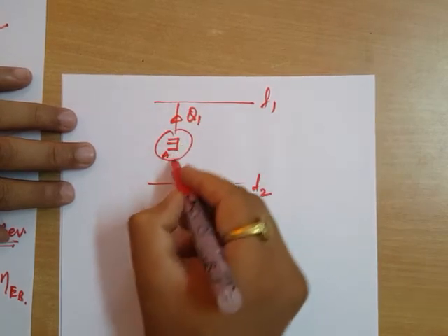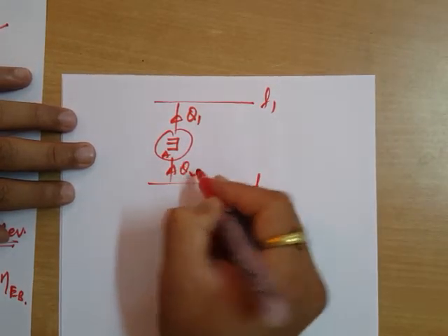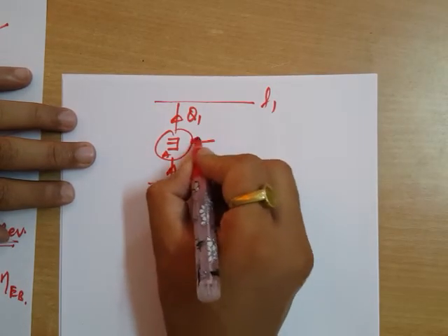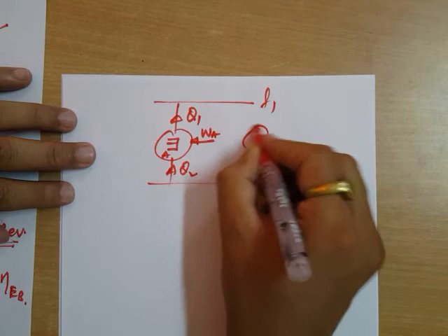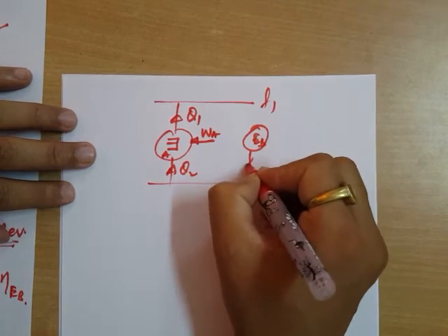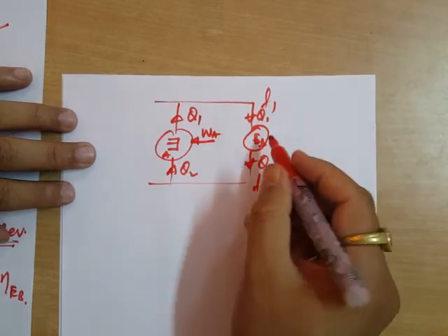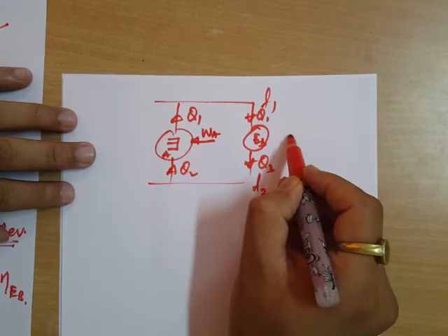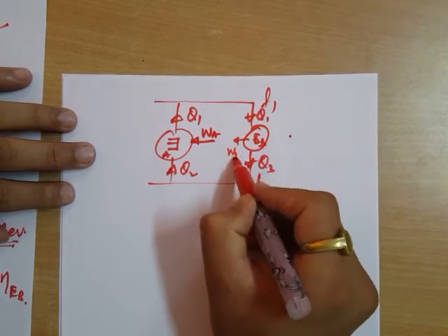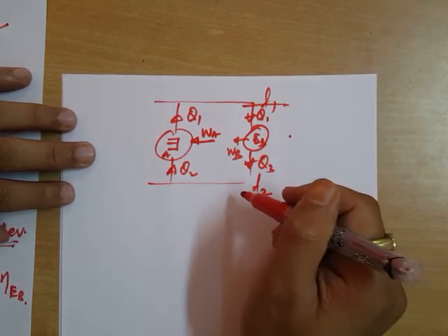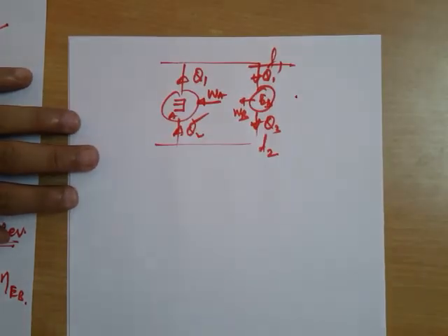All the heat and energy interactions will get reverted. So this is WA, this is my engine B, this is Q3, this is Q1, and instead of writing WB here, I will write it here, WB. As this is a reversible engine, I reverted it.